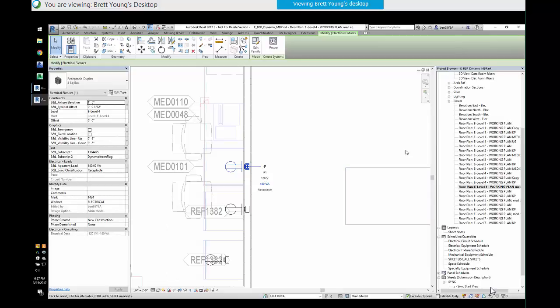If the equipment moves after I've already run this once, the receptacle won't move at the moment. But a rule that I think would fix that is the receptacle within 3 feet of the source, for example, right? If not, flag it or delete it, or do something. So that's the rule I think would fix that problem. But right now, you run this, then the equipment moves, the receptacle is going to stay over on that wall, and it's not going to be near its friend, but at least you'll know what it's trying to power.